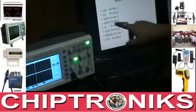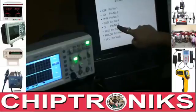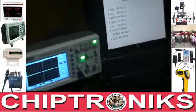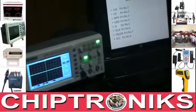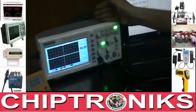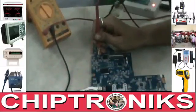Now after you receive these 3 voltages on the BIOS IC, you check the signal input pin. This is actually the data input pin, which comes from your IO IC, and the clock is pin number 6. This clock also comes from the IO IC. Clock and data we always need to check with the oscilloscope, not with the multimeter. But I'll show you, this is not actual testing.